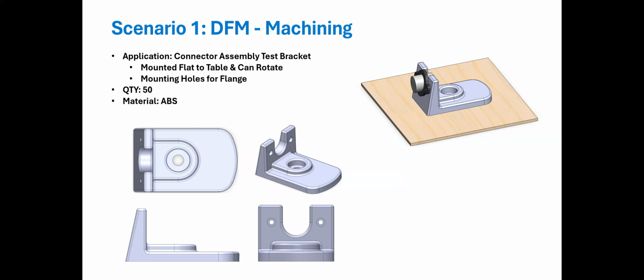Our customer initially thought he wanted to counterbore it, but after explaining that you can just mount your screw directly to a flat face instead of counterboring it, he preferred that because it saved on overall manufacturing costs and reduced an operation.